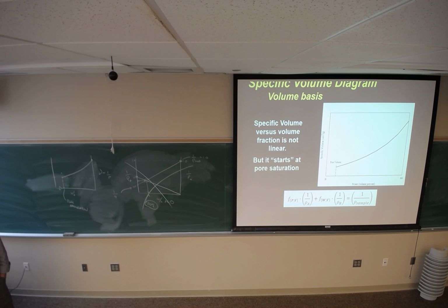What else can I do? I might be able to change the shape of the particle. If I have flat plate-like shapes, they might pack to a higher density than spheres, for example, right? So I have different techniques for changing the packing efficiency of the powder. Are you good with that? All right. But I'm pretty much stuck with wherever I start. So if I start with A16 and I'm not blending particle sizes, I'm going to have a certain packing efficiency that is based solely on the degree of dispersion. Okay? If I disperse the system, my packing efficiency increases. If I flocculate the system, my packing efficiency decreases.